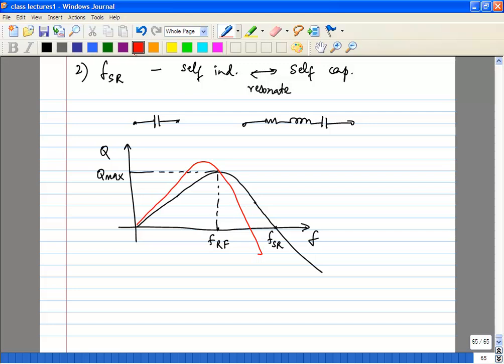and that will help you understand the trade-offs in inductor design. Yes. Suppose you are designing a transmission line for a given substrate with a given epsilon value. We'll have a particular track width for a given impedance. Suppose this has to be interfaced with a given transmission line. Then that track width will be governed by the impedance that we want.